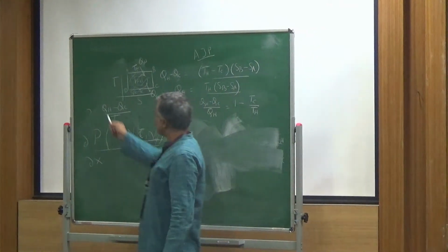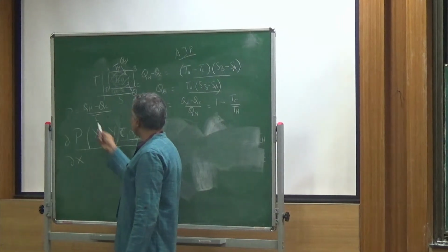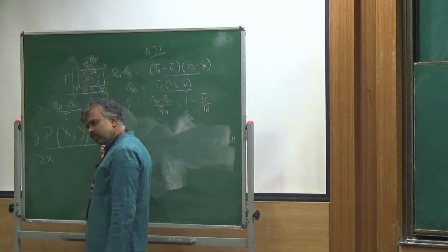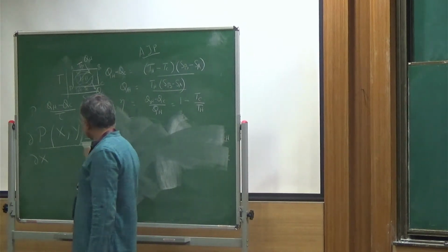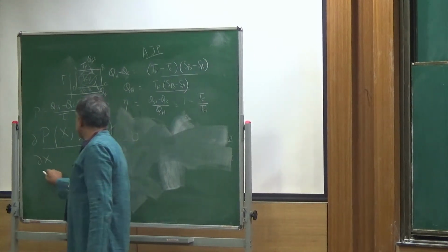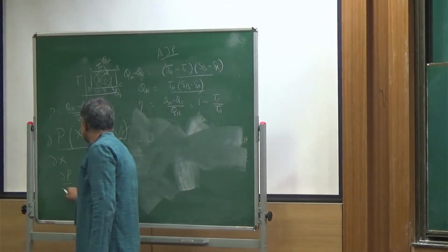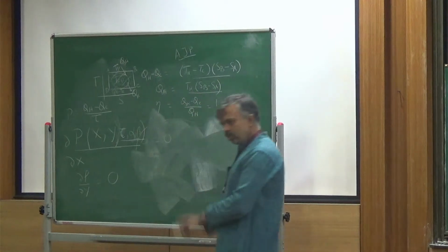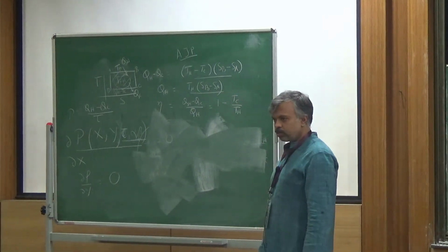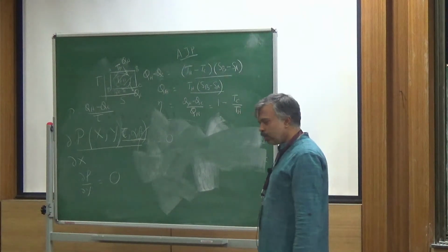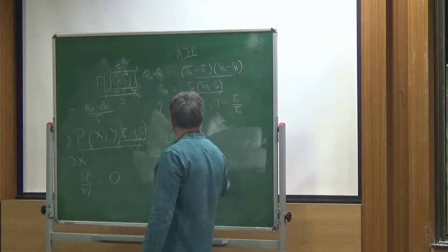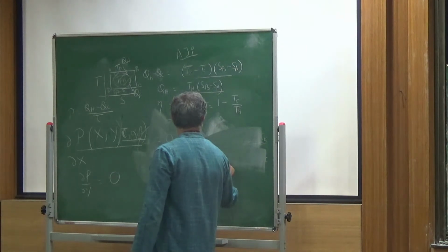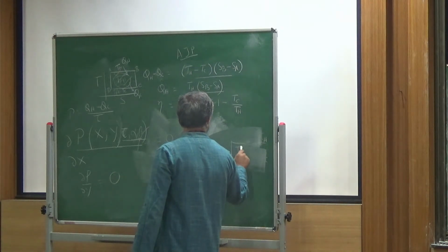With this x, y, finally you will get a function of x, y, the cycle time tau, and the conductivities alpha and beta. Set this to 0, and similarly this will give you another equation, simultaneously true. From this you actually get what I mentioned earlier, beta, 1 minus root of Tc over Th.